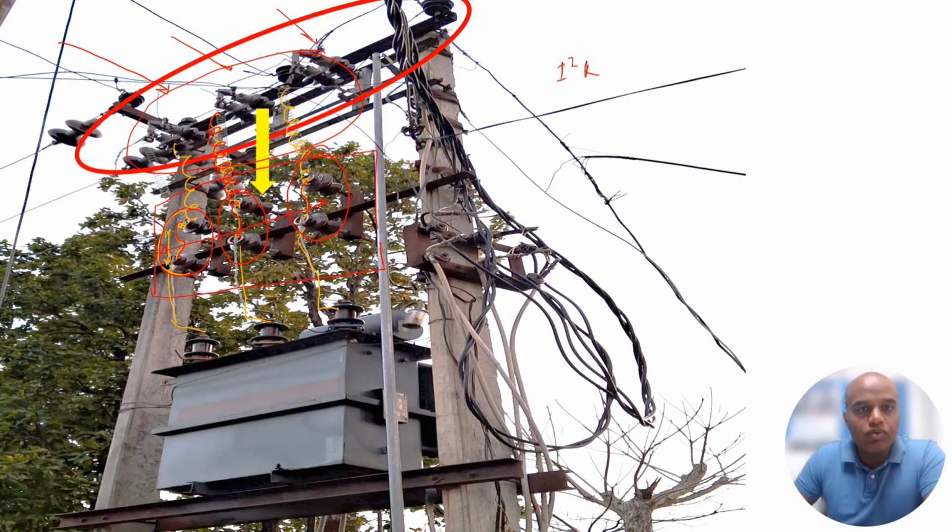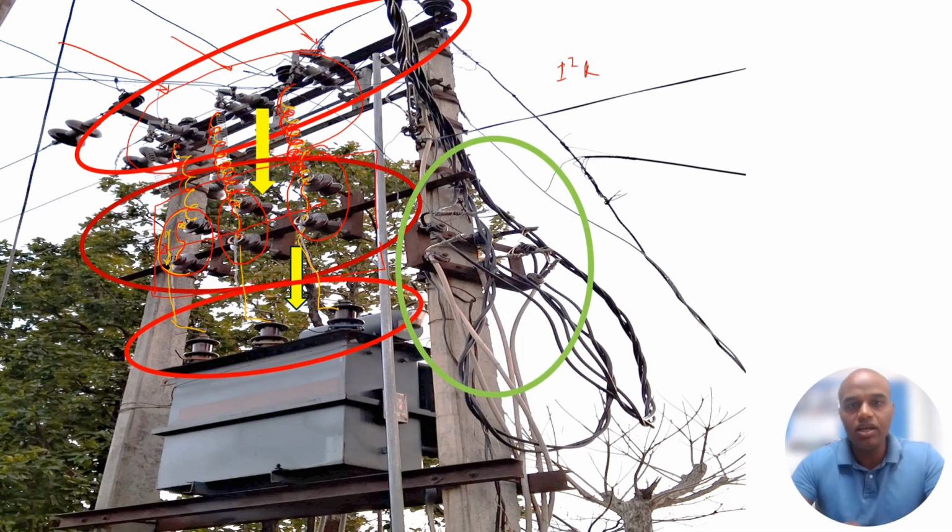These spiral wound shapes are given to provide strength to the wire which is coming down towards the insulator, because they are hanging wires and should not get in touch with the pole and the other parts of the pole. So to provide this strength, it has been provided in terms of this spiraling, and from here it comes down to the high voltage bushing side. And from here we can see the outgoing 440 volt supply, because this is the transformer that steps down the 11 kV to 440 volts. So this is the outgoing supply which goes for my residential load purpose.